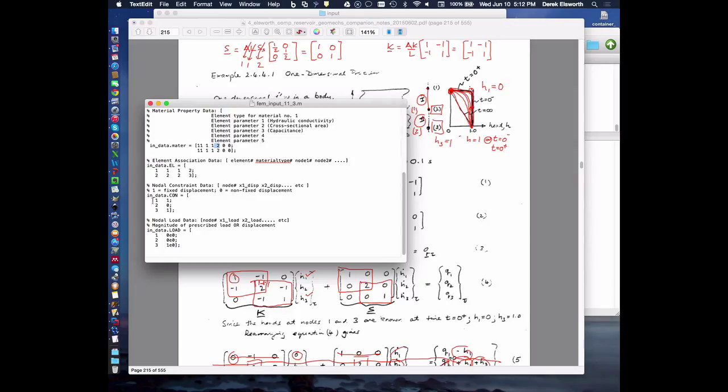What were the boundary conditions we fixed? We had a head at the top, node 1, which was equal to 0 once we started. We had a head at the bottom, which was equal to 1, which is constant. And we didn't know what the magnitude was in the middle, so it's undefined. And so this is 1 at the bottom, 0 at the top, and 0 flux in the intermediate part. So yeah, it is exactly the subroutine that we need to be able to solve the system.